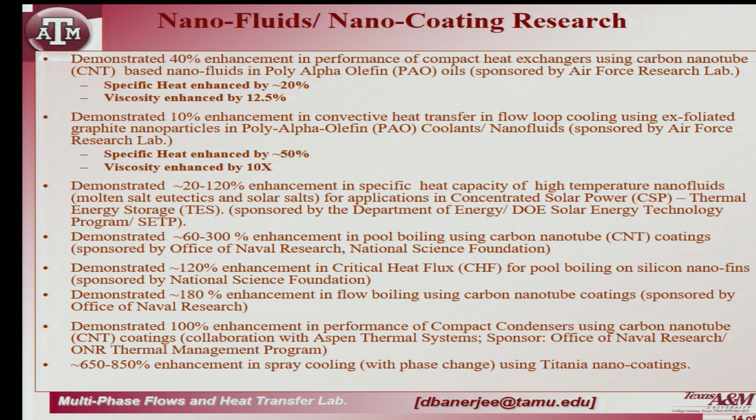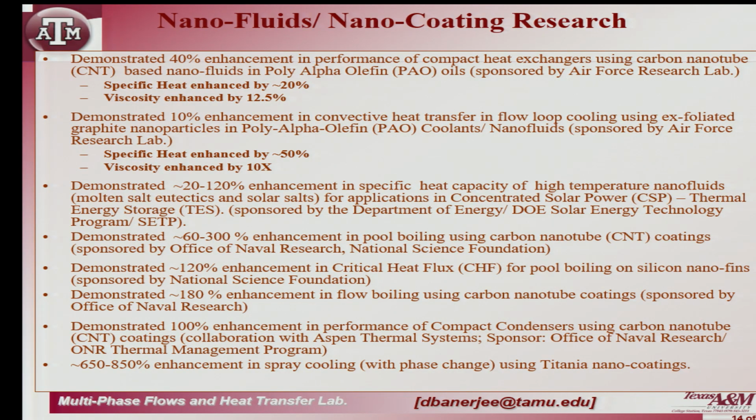And we said, well, the molten salts have very bad thermal properties, maybe by putting nanoparticles in it you can improve the heat capacity and the thermal conductivity. Okay. So DOE gave us a grant and we put different types of nanoparticles, and at this point we had a better understanding of where the enhancement was coming from, and so we were able to enhance the heat capacity anywhere between 20 to 120% in a very repeatable manner. We could repeat the experiments this time and show that it's a repeatable synthesis protocol.